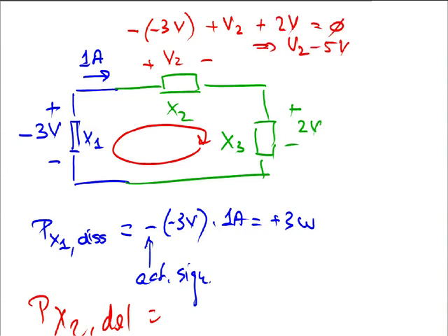Okay, so what's the current running in X2? Well, it's an amp. Now V2 equals minus 5 volts. Is this passive or active sign convention? Here it's passive, right? So for component X1, the arrows and pluses and minuses worked out to be active sign convention. For component X2, they worked out to be passive sign convention. You have to look at every component. It's not that you can say, well, I don't like this active and passive, that's two different things, it's too complicated, I'm always going to use passive for whatever. You can't do that. For every component, it comes out whatever it wants to be.